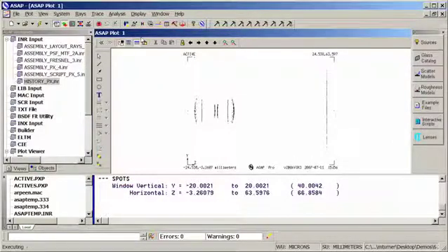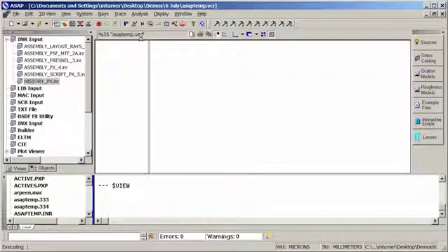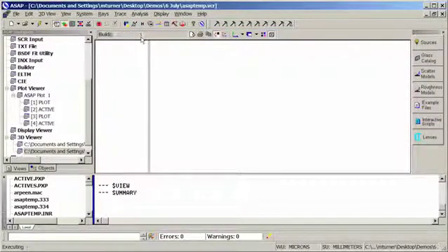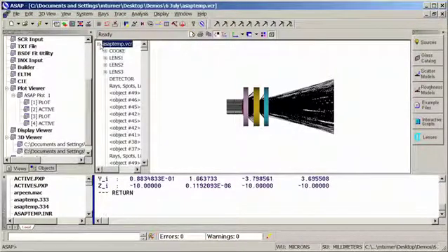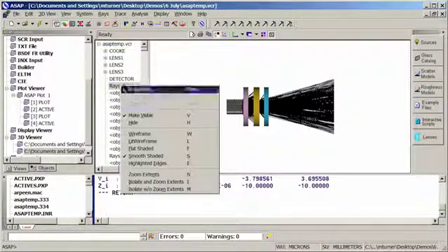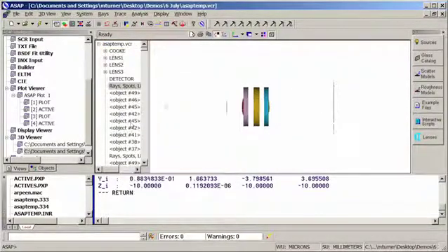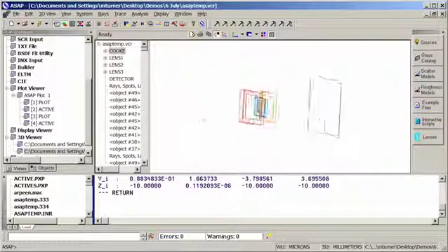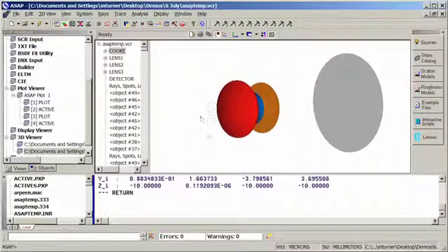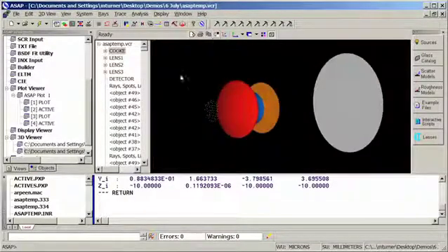And what we see here are the surfaces that rays were on just before they exited the system, as well as those rays that are on the detector. Initially this looks a little bit scary, but if I open the list of objects, let me hide all of the original ray paths. And I'm also going to hide the mechanical structure so it will allow us to see things a little bit more clearly. Now let me rotate and zoom a little bit. And what we see on these surfaces, these little dots, let me change the background color, make it a little easier. These are where some of the Fresnel reflections were then lost from the system. These were rays that didn't make it through.